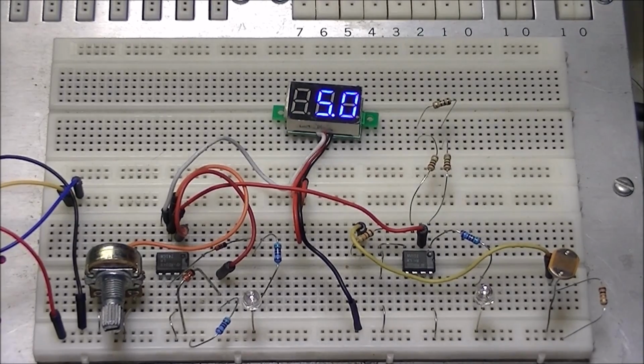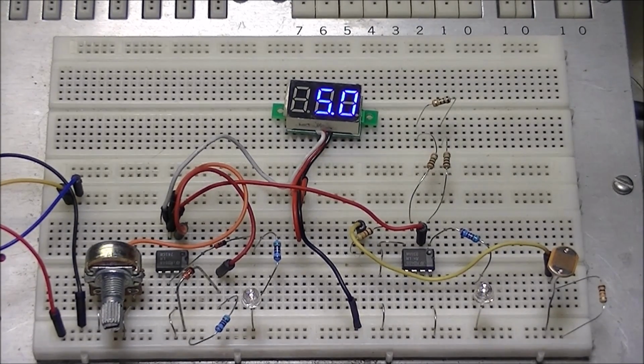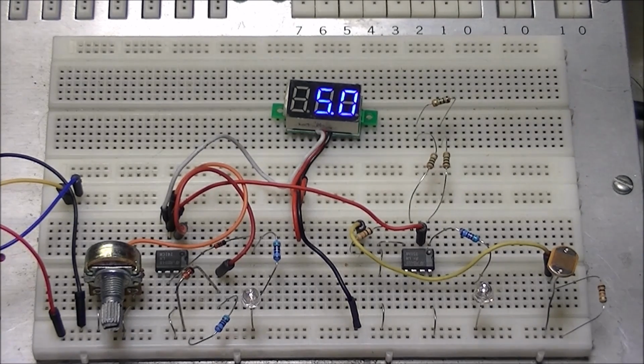Without comparators, we could never connect the digital world to the analog world. They're the basis of analog to digital conversion and several other ideas that we use every day in microcontrollers and electronics. A comparator, as the name suggests, compares two input voltages, being nothing more than an operational amplifier with no feedback.